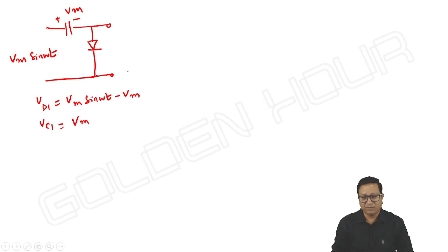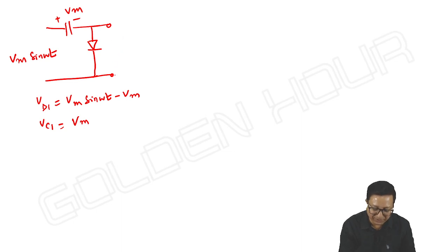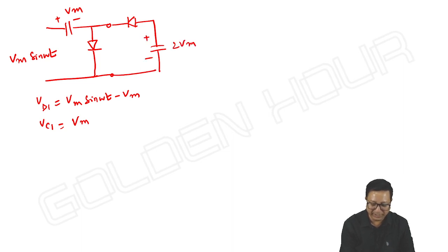In voltage doubler, what we did, we gave its output as input to a positive clamper. So positive clamper, what I am doing here is, this is what we took, so that this capacitor will charge up to 2 Vm with polarities this way. We are well aware of it.